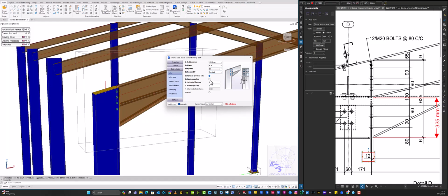All right, distance from previous bolt gauge, then horizontal distance, that's what we want. So your horizontal distance is this one here, from the other side of the web to the other side of the web. And here we've got 90 and we want 80. So let's put 80 there. And then number per side, it's 1. So we've got 1 on each side of the flange. Okay, so let's go to bolt groups. Now, here, what we have here, we've got lines of bolts.